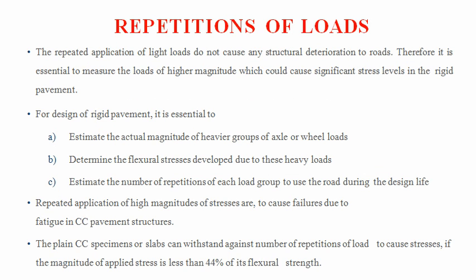Next, we shall discuss the repetitions of the loads. The repeated application of light loads does not cause any structural deterioration in rigid pavements. Therefore, it is essential to measure the loads of higher magnitude, which will cause significant stress in the rigid pavements.